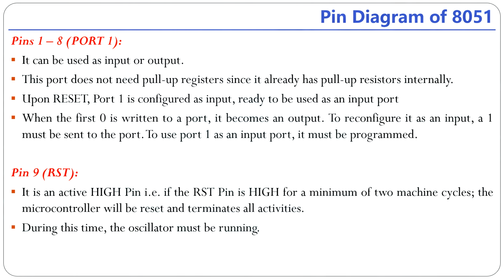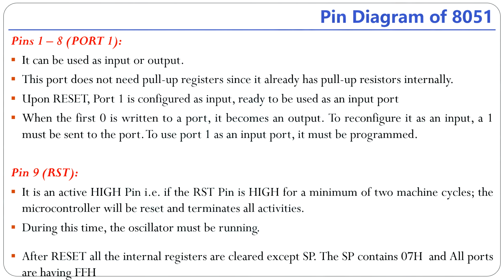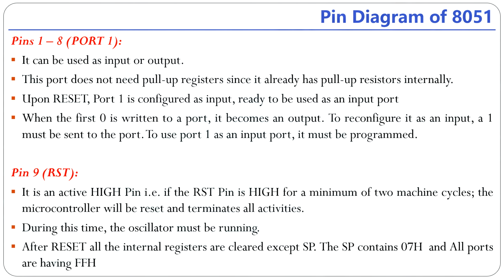During this time the oscillator must be running, and after reset all internal registers are cleared except the stack pointer and ports. The stack pointer has 07H after reset, and all ports have FFH.